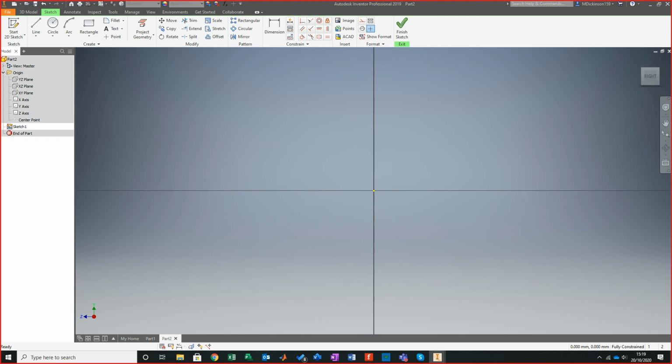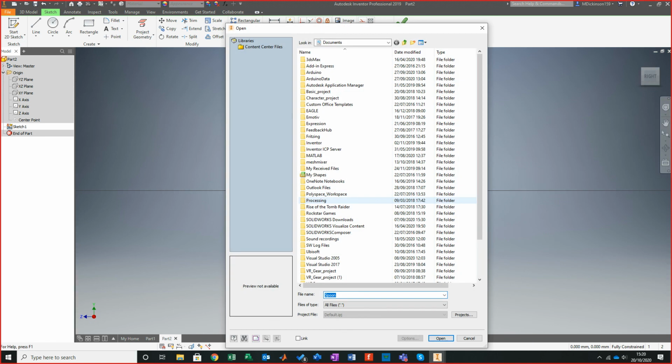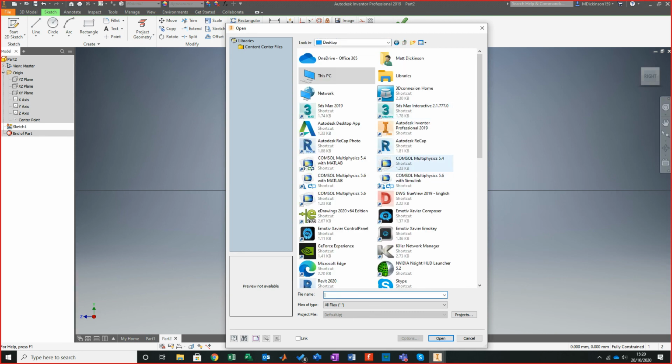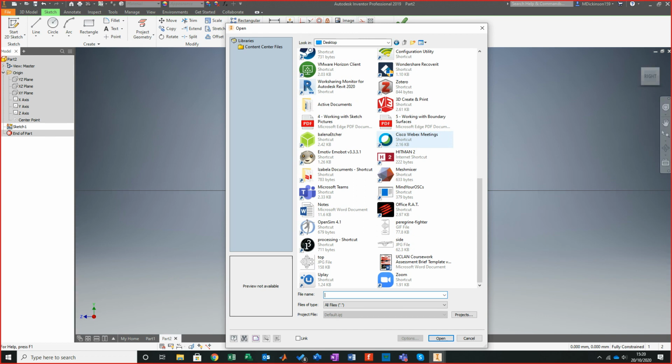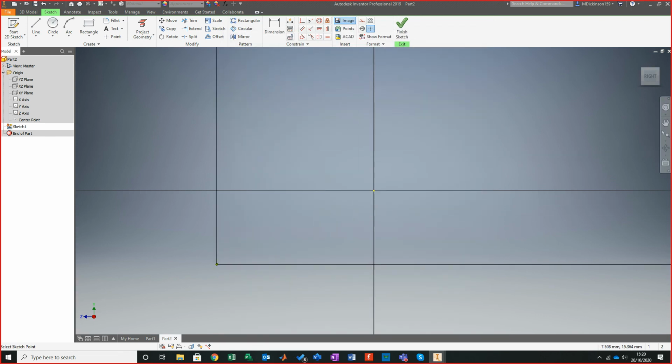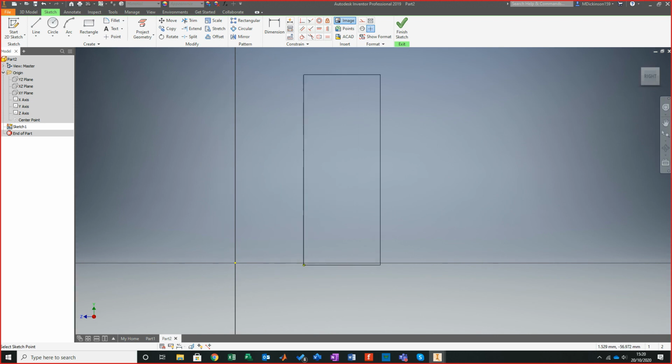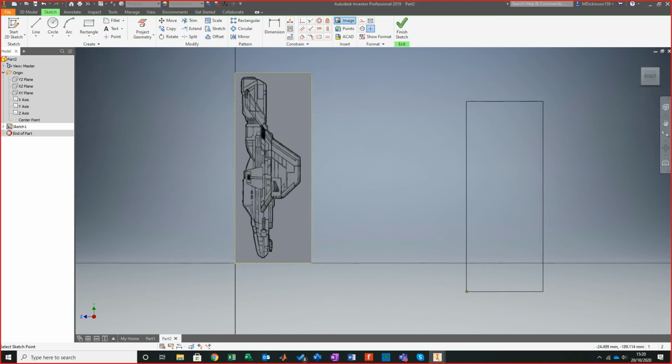And typically on SolidWorks it is insert, tools, sketch tools and picture. Here it is image. So all I'll do is go to my desktop and I'm going to go side image, click OK. Now you can see there how it's been brought in. I'll bring it there.